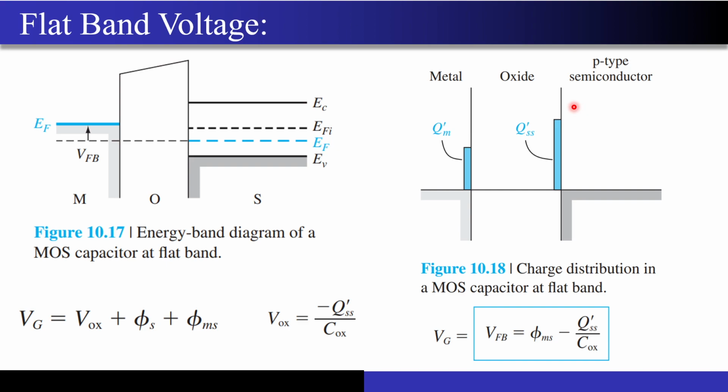right? And how do we get to the threshold voltage, right? First we go through the depletion, then we increase the positive voltage at the metal side up to such an extent that the depletion region gets maxed out and we get the electrons over here, right? So now if the depletion region is already there, I don't have to apply any positive voltage. That clearly means that to reach the inversion I have to apply a lesser gate voltage, that is lesser metal voltage.